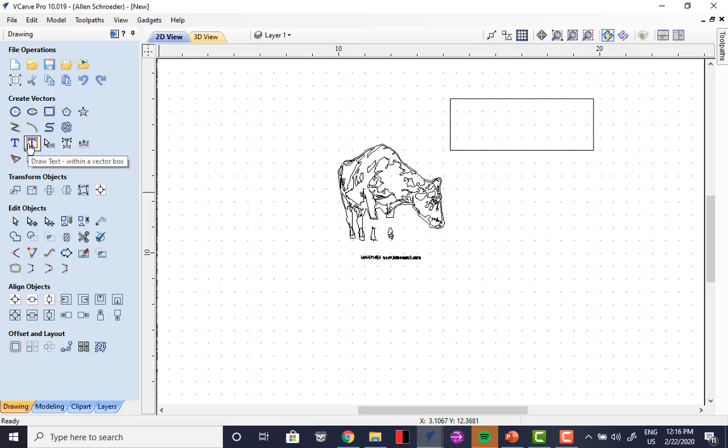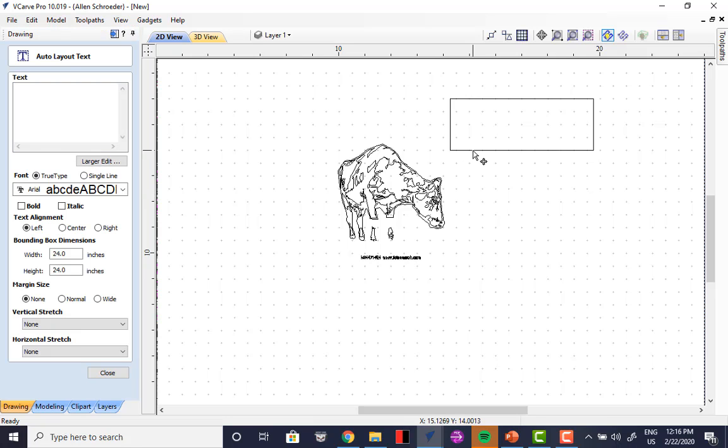If you hit this text box here and highlight that right there, give me a name. John, Skylar. S-K-Y-L-A-R. Now see how it fit exactly in there? Now one thing, anything with a Y, I don't like letters like that because they hang down and really screw up your V carving. So what I would do is I would capitalize everything.